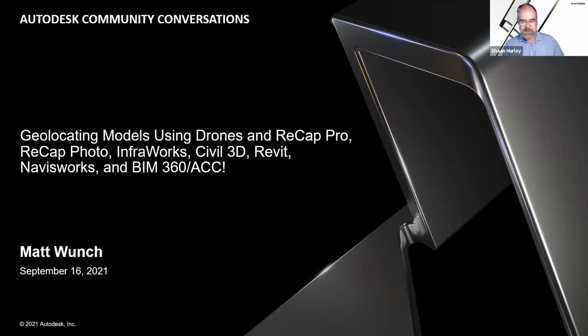And actually what I didn't show was that, through this process, once I trimmed out what I didn't want, I exported this to an FBX file. Save it wherever you want. You may want to mess around with the decimation to try to find a sweet spot between file size and visual clarity, something to take a look at. But again, I've already done this in the background prior to this. So let's jump back to InfraWorks and find our FBX file.